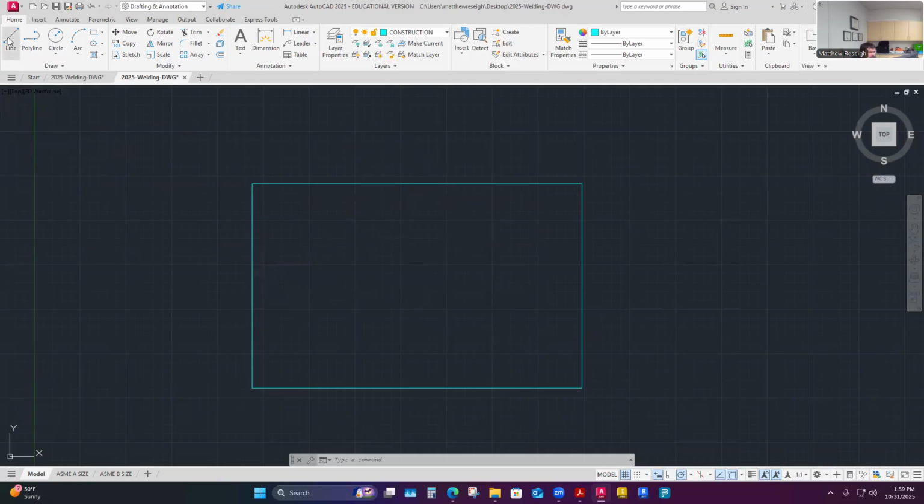horizontal. So I'm just going to pick the line command on this now. Line, where do I want the line to start? I'm going to look for that midpoint grip. If I even get close to it, it starts showing up, and once it shows up, it'll snap to it. Even if I'm away like this, it'll snap me to that. Once it recognizes a snap, it's going to target me to go there. So no matter how far away you are, if that snap's showing up, it's the one it's going to snap my line to. And that's just what happened there.